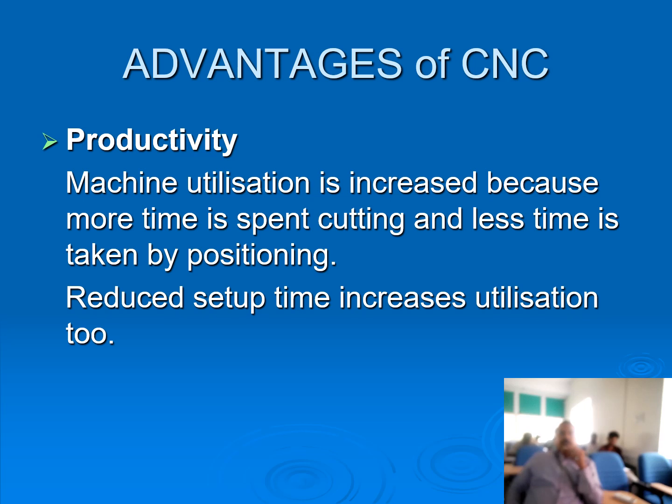And the second point is reduced setup time. Because once you make the setup, the machine can continuously run the program and make the components. So reduced setup time increases utilization too.